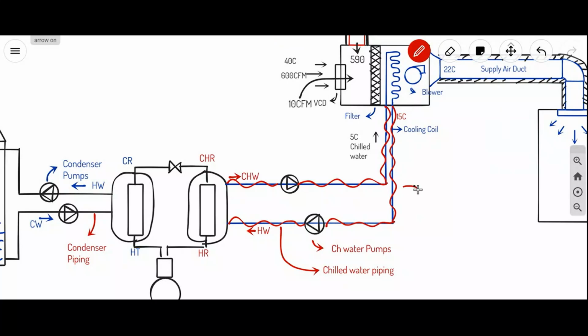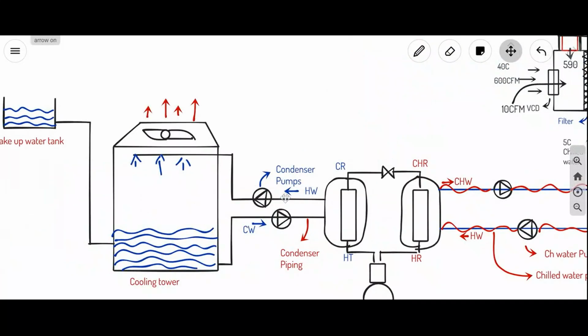This insulation is puff insulation. So do we need any insulation here? No, sir. Insulation not required for that area, sir. Yes, why? Because it's nearly ambient temperature, sir. Those are dealing with ambient temperatures. Okay, very good.